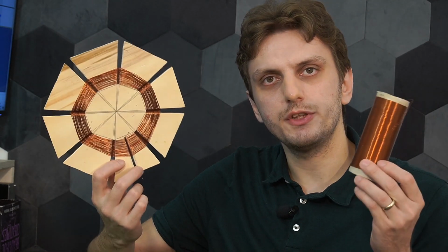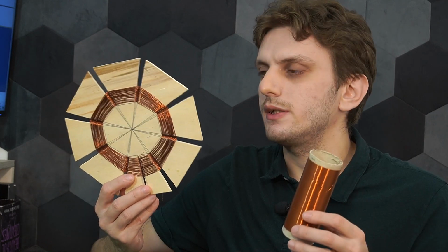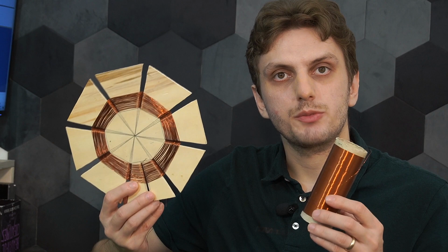And there's two ways we could try to do that. On one side, we could go for the solenoid shape, so single layer and multi-turn, and on the other hand, we could go for the spiderweb shape, single turn and multi-layer. The main difference between the two, if you get them to the same diameter, is the way in which the radiation spreads out from the inductor.